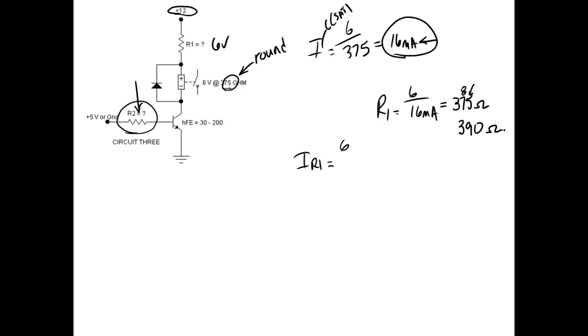Okay. And of course, y'all didn't know, but now you do know, right? So when you're looking at the load, you're looking at trying to maintain the current that is specified to run, right, as close as we can. So we'll round on that guy. Okay, so let's use 390. Whatever y'all use, it's going to work out pretty close anyway. So now I calculate IB sat.